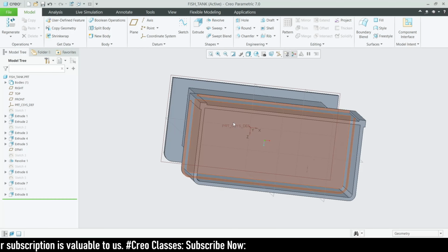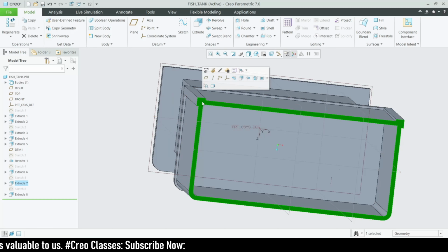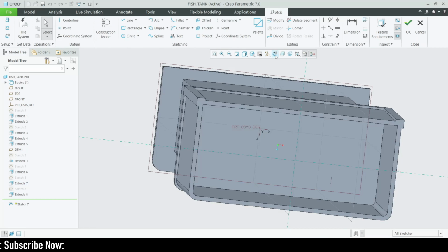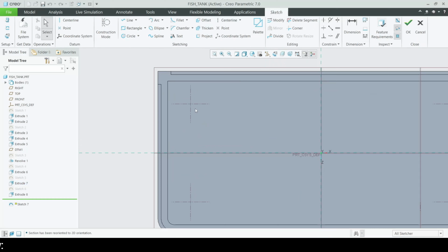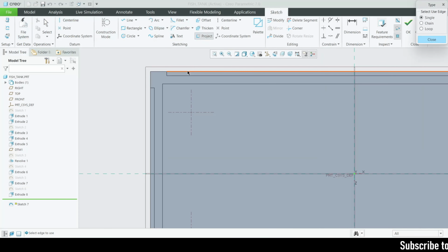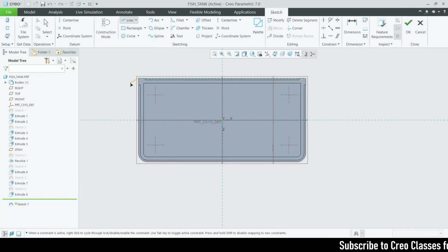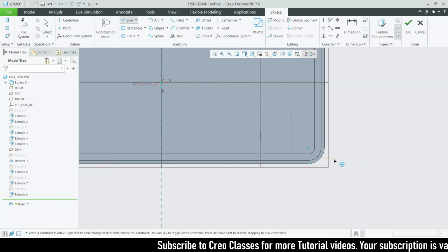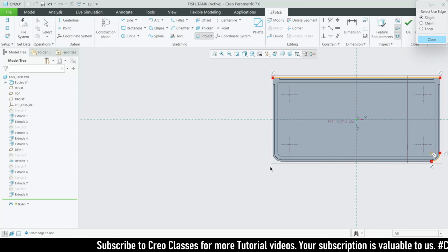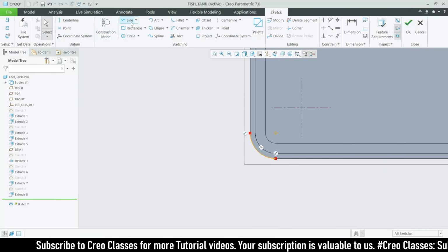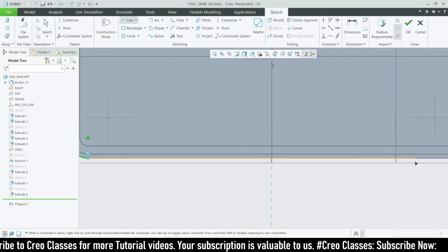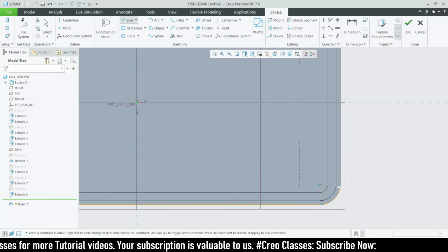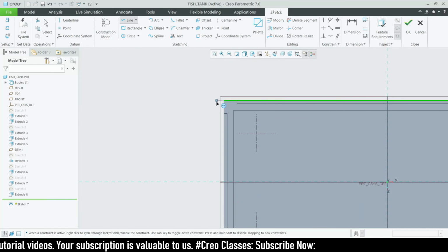Okay, so then we just want to create the top face here. So for this, let's go for the sketch, and the sketch view. Here I'm just going to take a projection, or we can directly go for the sketch. I just want to create a line like this, and we just want to take a reference for the circle. Sorry, we can project this. Then we can directly join these two curves with a line, right? Because we know the start point and the end point. Like this, we can do this.